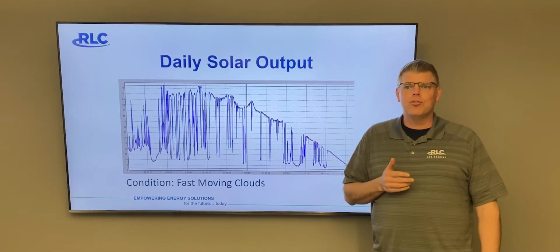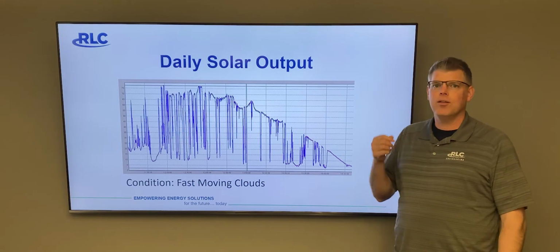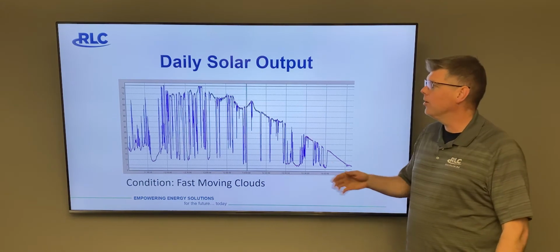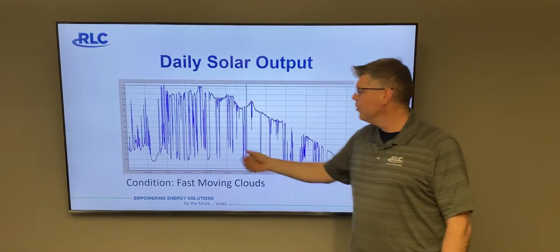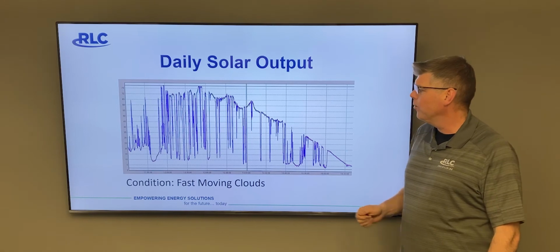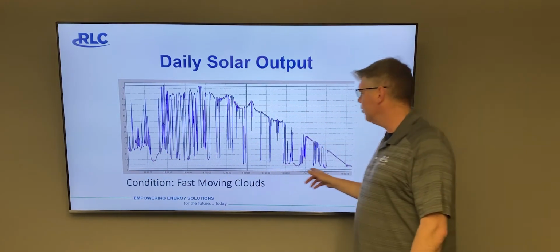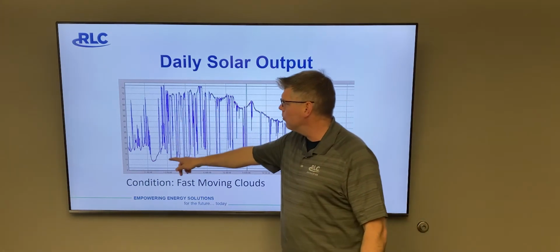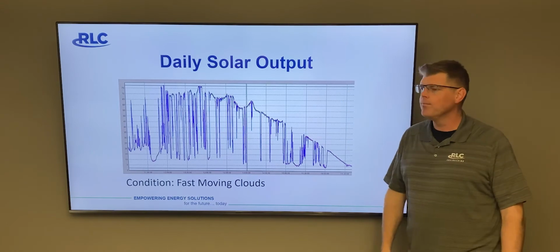In a distribution system, this voltage flicker comes from the stiffness of the system, and also when generation is involved, fluctuations throughout the day. We can see here a solar profile of a distribution project. Notice that it starts from around 10 o'clock in the morning and runs to the end of the day. But notice the big power fluctuations that translate through to the voltage.